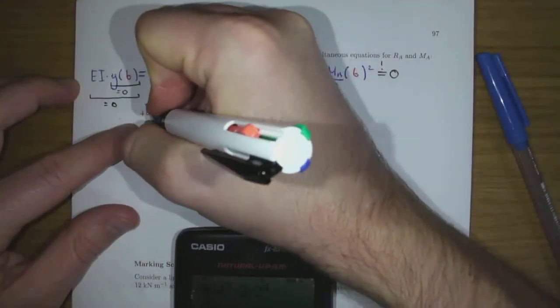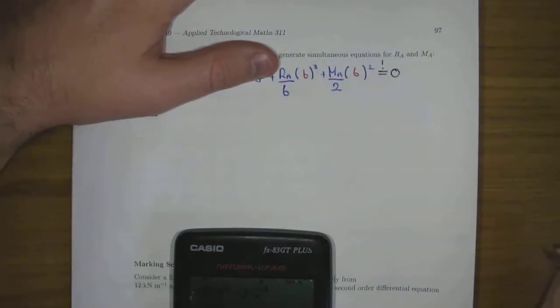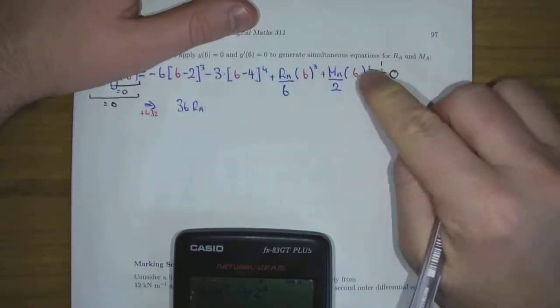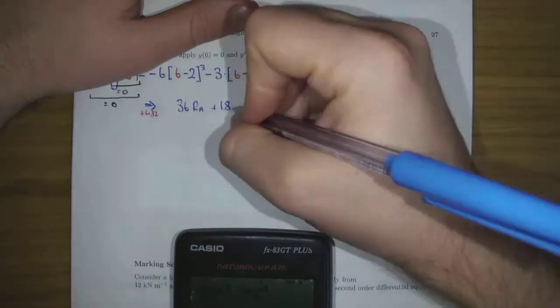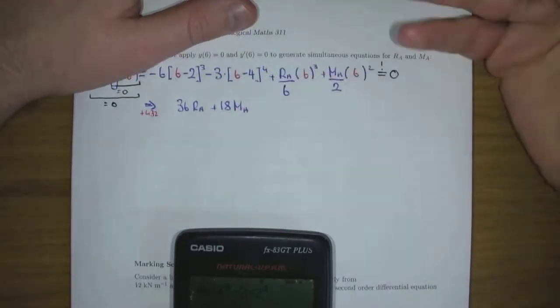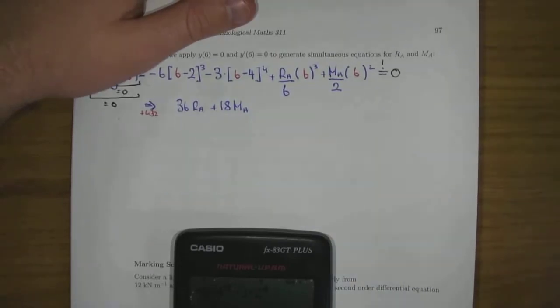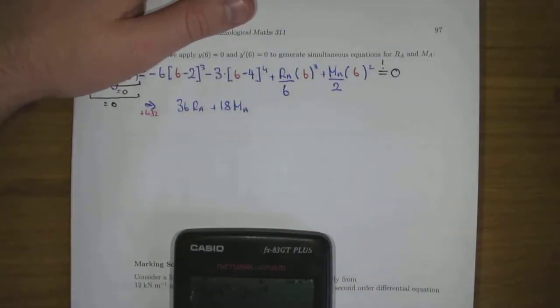Plus 432 to both sides, it gets rid of that. Now 6 cubed divided by 6 would be 6 squared, which is 36. And then 6 squared is 36 divided by 2 is 18. The numbers get a bit nastier here if, say, the span of the beam is 7, or even 5 or 4. So if you want, you could use Cramer's rule once you form the equations. I don't really want to see rounding, but if you are, 4 significant figures.